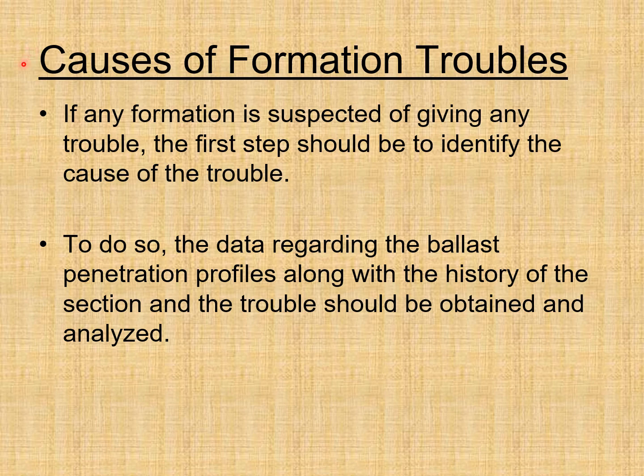Causes of formation troubles. If any formation is suspected of giving any trouble, the first step should be to identify the cause of the trouble. To do so, the data regarding the ballast penetration profiles along with the history of the section and the trouble should be obtained and must be analyzed.